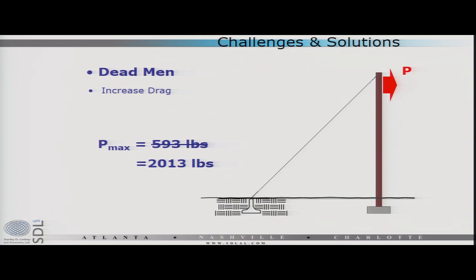So the question is, does greater embed length affect the capacity of the anchor rods for lateral resistance? And the answer is a little, because mostly what we're failing is the bending strength of what's above the concrete. So as long as the tension strength is adequate to resist the tension component, then it's all in how big the diameter is.